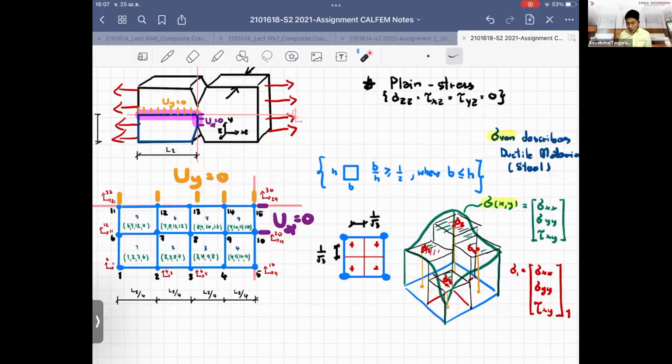We use the concept of the Gauss point, so it means we try to approximate the hyperplane, which is nonlinear, by using the constant plane of the linear within the element, right? So the more the Gauss points, the more the elements, and of course, when you increase the number of Gauss points, you have to increase the function of the displacement and so on, the more accuracy you have here.